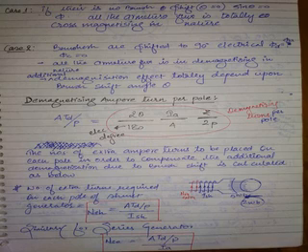Now keep number 2, phi c, the cross magnetizing component of armature flux, proportional to cos theta. In the previous case, you substituted theta is equal to 0. When theta is 0, phi d is 0, but phi c is phi a. What is the meaning of that? All the armature flux is cross magnetizing in nature.